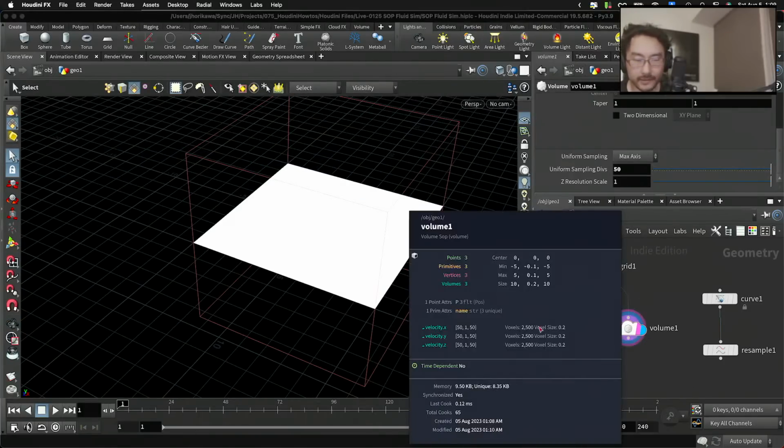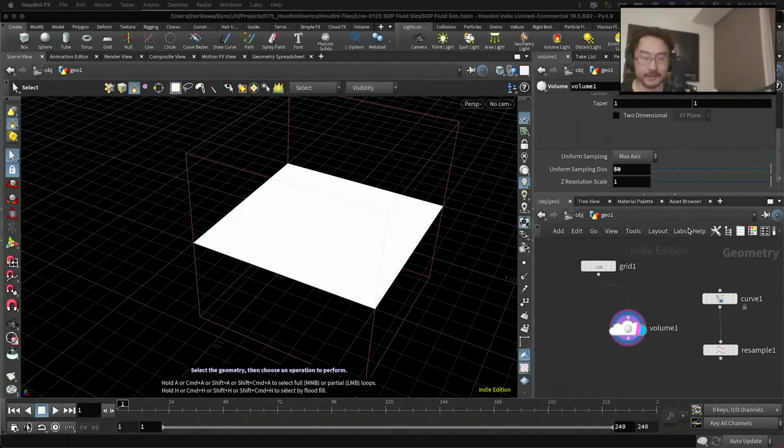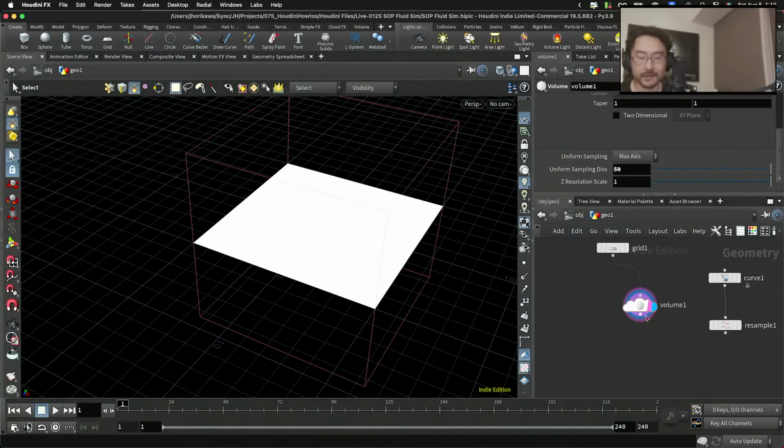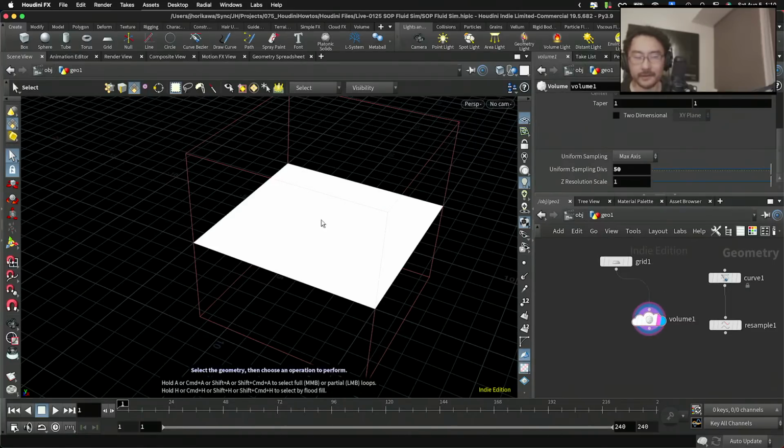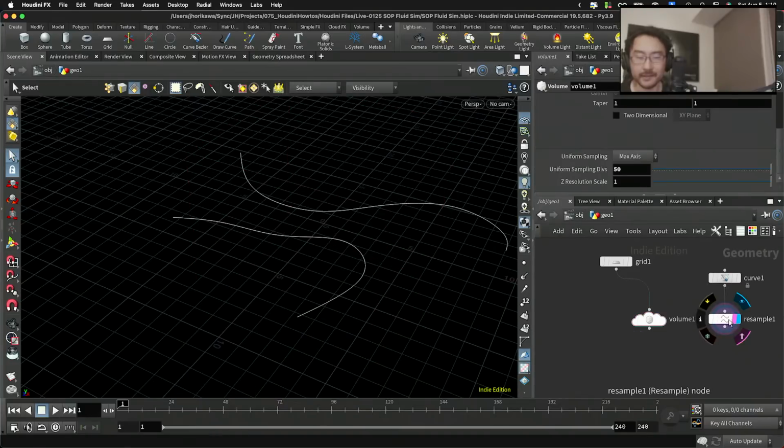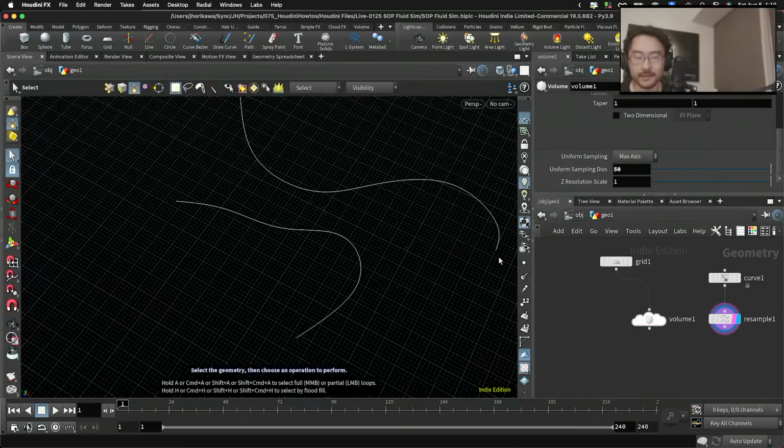And let's check the volume shape. So it's 50 by 1 by 50 for all XYZ directions. Okay, now it's time you could start creating a vector field. Modify the vector direction of this volume using this basic curve as the base direction.